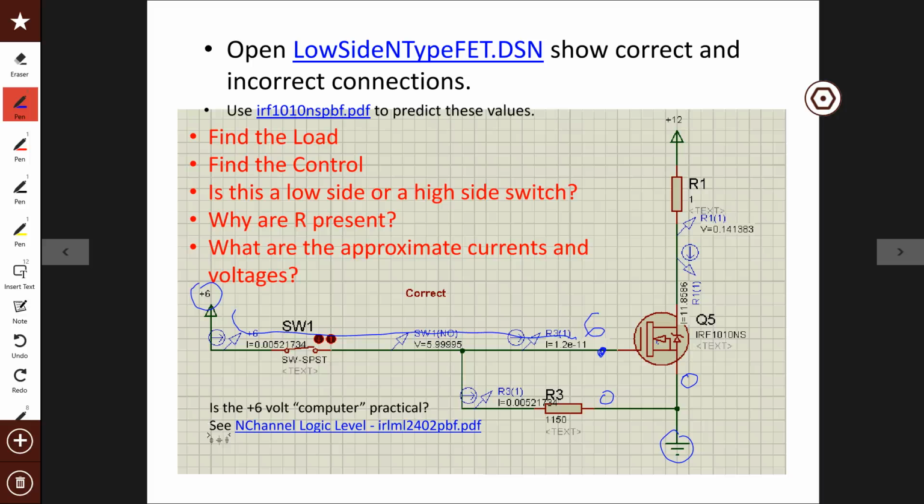Okay, and so now if you have 6 volts back here on the back side of this resistor, you can approximate the amount of current that goes through here, because it'll be tail voltage 6 minus head voltage 0 equals the resistance, which I think is 1, times the current that goes through there. So you can solve for the current that goes through this approximately, right?